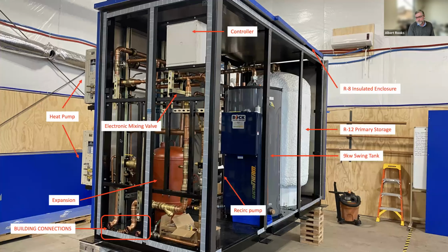And then we can start looking at, we can kind of do our own research and development in how to turn it into a glycol loop and still retain the same. But if you're in the Northeast and in climate zones 6 and 7, I would work with a larger capacity heat pump with a glycol loop and a heat exchanger away from primary. And the good news is there are products to choose from now. It's just hard to find the designers and the people to help you design a project successfully.